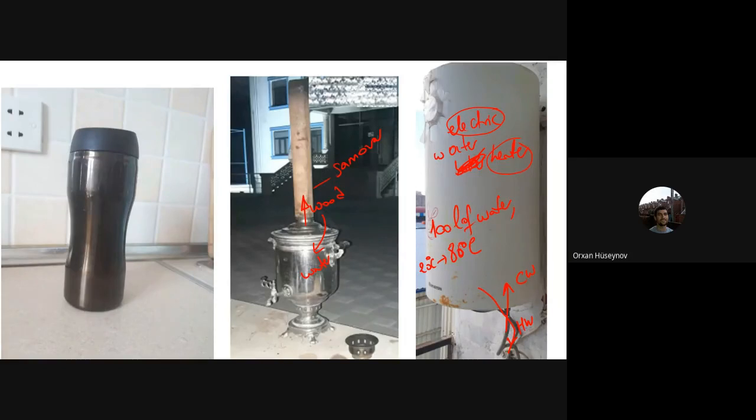And one more thing here is that you should select your materials very well, because here you have heat loss. The system loses heat to the environment. So here you need good insulation. Otherwise, because of heat loss, the system will not use the same electric power that has been calculated. It will be more than that. Therefore, insulation is very important. In some of ours, you don't have good insulation. You can see that after some time the water cools off, therefore you are burning the wood all of the time.